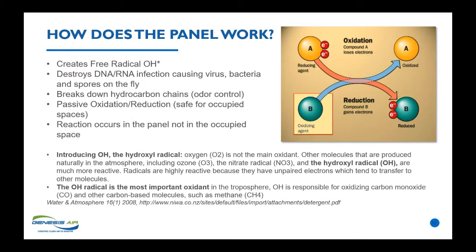What the free radical does is it breaks down the DNA and RNA of the infection-causing virus, bacteria, or mold spores on the fly. If it's odor control, and a number of Genesis PCO jobs involve airports, heliports, places where outdoor air is coming in affected by generators. We do a number of casinos with environmental tobacco smoke. By breaking down the hydrocarbon chain with an oxidation reduction reaction, you rid yourself of the odor that was a problem. It's passive. Genesis PCO products do not have the reaction occur out in the occupied space where the people are. It occurs only in the panel.